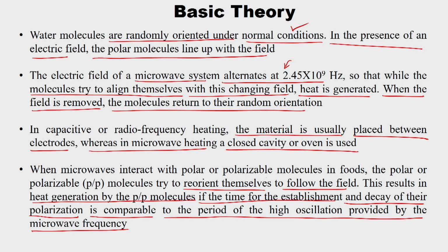So, you need to give that particular time for the molecules to get aligned, and due to that collision they produce the heat. So, if the given microwave frequency is not enough for them to align, or the amount of time with which the microwave frequency is applied to the dielectric materials to produce the heat is not enough, these two are very much important to get the particular heating done. So, it has to be established for a particular time, and it depends on the power you give, the frequency you create as well as the time at which the frequency is applied to the dielectric materials, based on which your heating will be done.